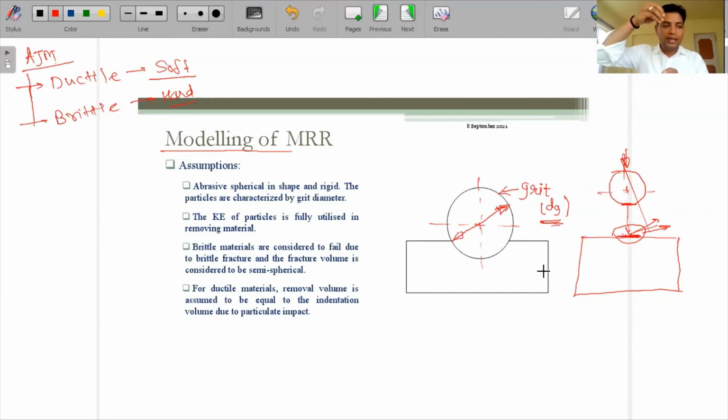This is simply a kind of rubber, and when I impinge it over the workpiece surface, as it impacts, it moves in any direction, guys. As this rubber hits the workpiece surface and goes in any direction, similarly the abrasive particle will behave. They will come in contact with the workpiece surface and move in any direction. Or there is a possibility that if it has a very high strength, as we are using very high velocity along with that, it will impinge inside the workpiece surface, because it will create some indentation, and that will remove the area.